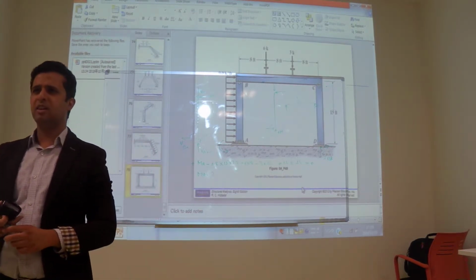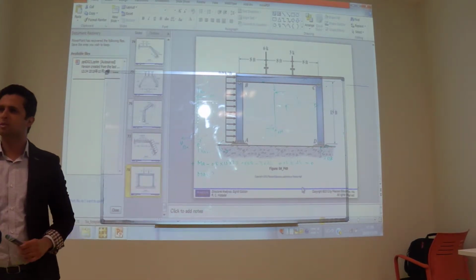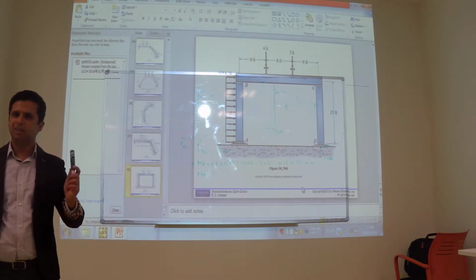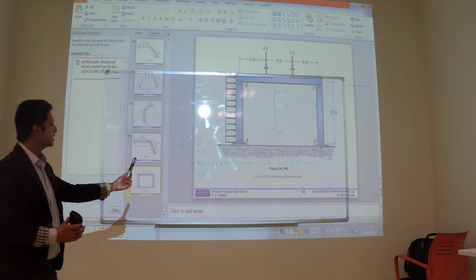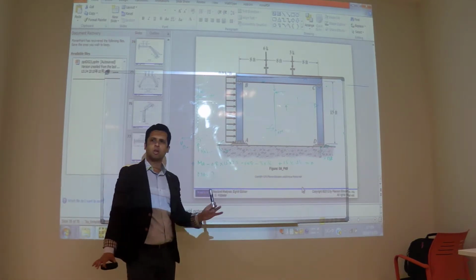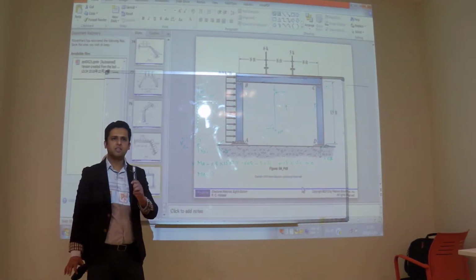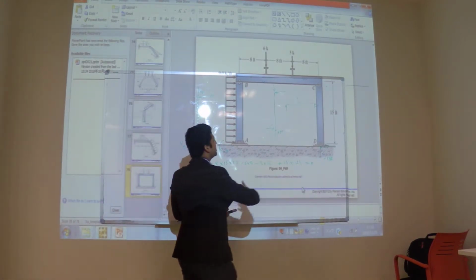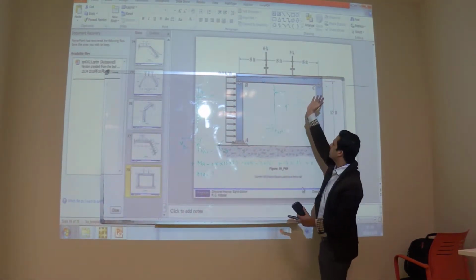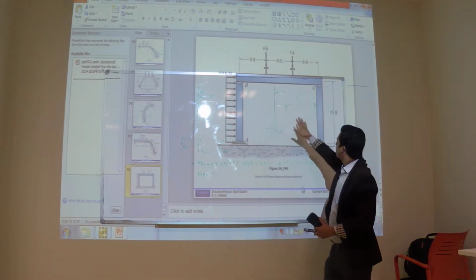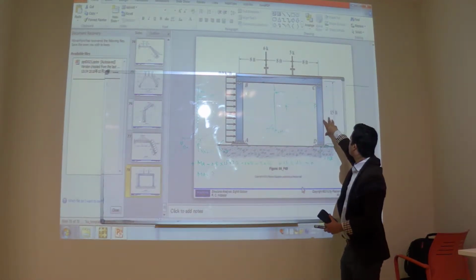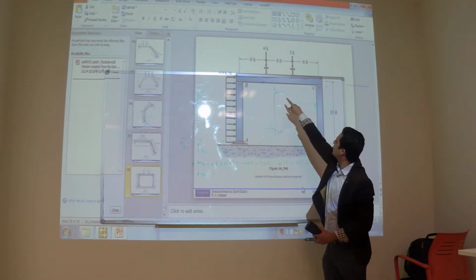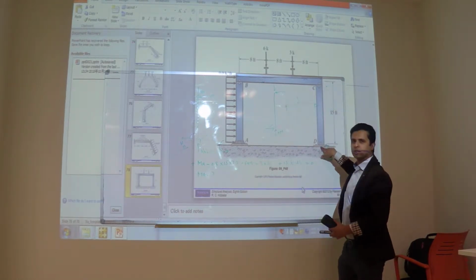Is there need of homework, or you can do it? Well, try this at your home. But this is the only trick, the moment, which I explained to you right now. First, divide into components, like this member separate, the other member separate. Apply sigma fx, fy for each, and you will get the whole vertical reaction up to this point.